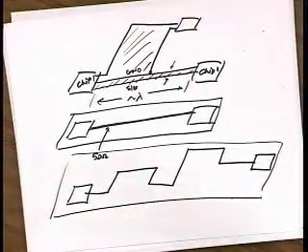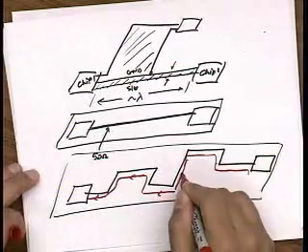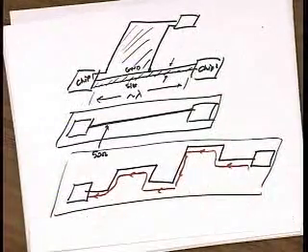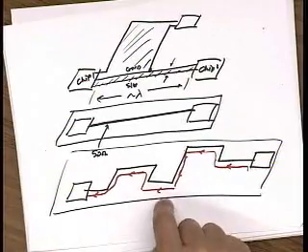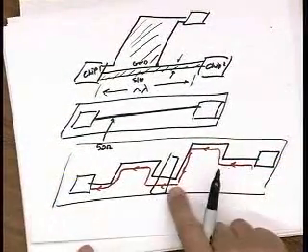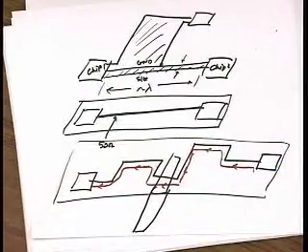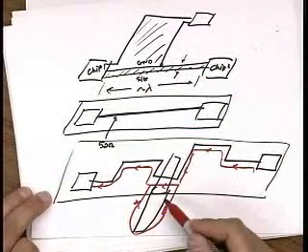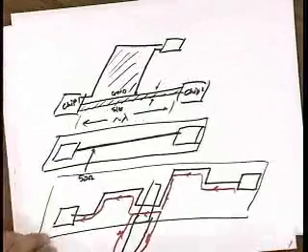the physics tells me that the return current will flow right under, more or less right under that signal line at high frequencies. At low frequencies it goes everywhere. But at high frequencies it will follow my conductors everywhere. And this is why it's so important not to have cuts in your ground plane. Because if you inadvertently, let's say you decide, oh, you know what, I've got to put a hole here because I need to have a via go through. All of a sudden this current can't go directly under the conductor, and let's say this hole is really large. So now this current is forced to go around. And what happens? I've created another loop, and I can pick up interference and transmit interference through this loop. Okay? So watch your ground planes when you do microstrip transmission lines.